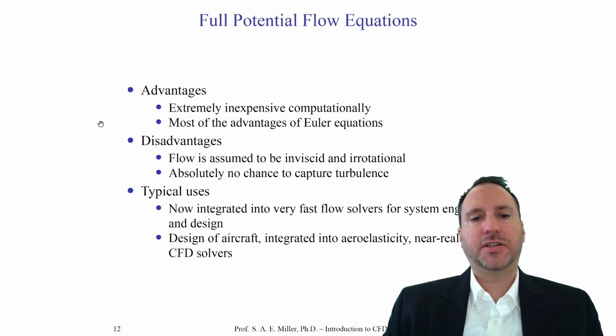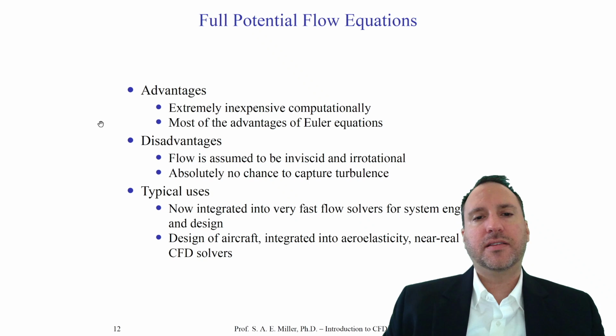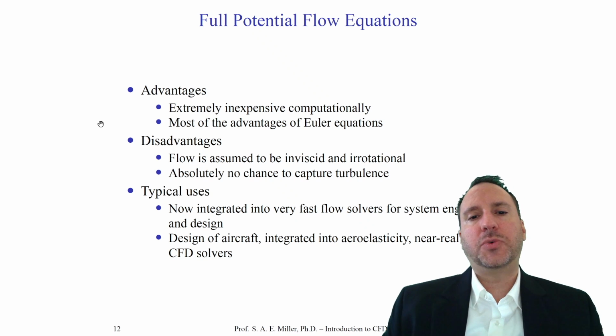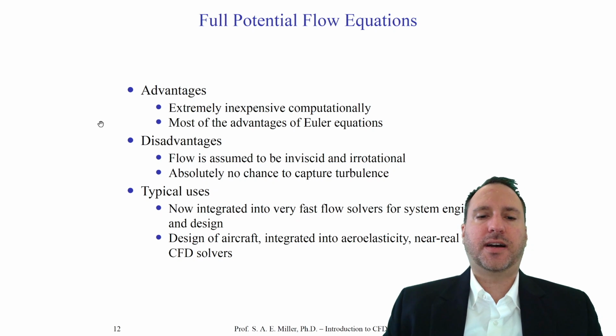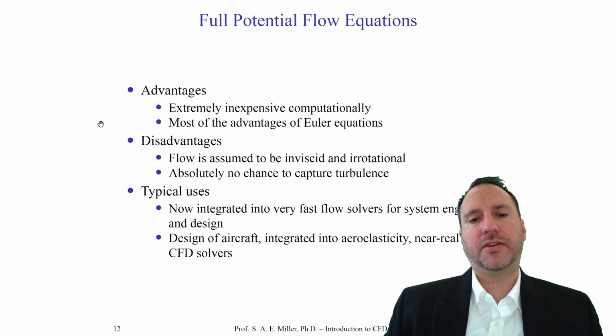Typically, this equation is used and integrated for high-speed compressible vehicles for system engineering and design problems. These types of equations might be integrated into a single processor solver, which might run thousands, if not millions of times for a single aircraft type of design, or any other type of vehicle where these types of equations are appropriate. Once they down-select to a design, they might run higher fidelity solvers with Navier-Stokes or Euler with turbulence models to find the final design where they might go into a wind tunnel for testing.